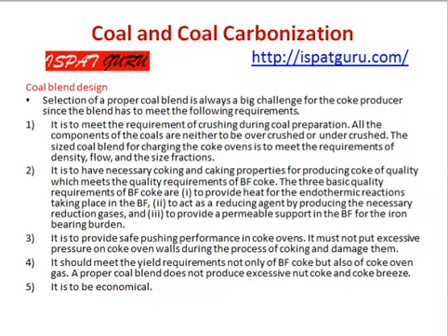Selection of proper coal blend is always a big challenge for coke producers since the blend has to meet the following requirements. It has to meet the requirements of crushing during coal preparation. All the components of coal are neither to be over-crushed nor under-crushed. The size of the coal blend for charging the oven is to meet the requirements of density, flow and size fraction. It is to have necessary rank and coking properties for producing coke of quality, which means the quality requirements of